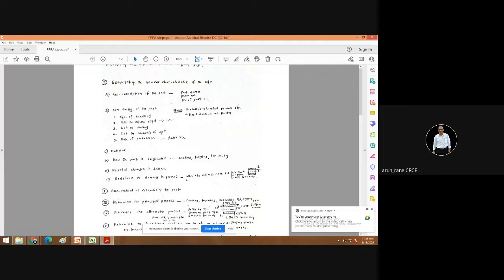what is the general configuration of the part. So in general configuration of the part, we discuss how the components are to be handled. So for that, you need to calculate the weight of the components. If the components are heavy, that is if it is more than 5 kg, then one person may not be sufficient. If the component is say 15 kg, then you may need devices like hoist, crane.